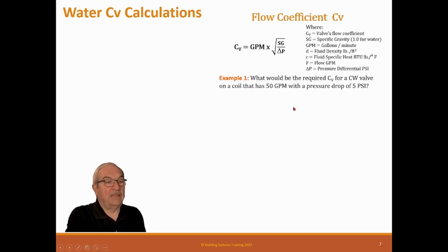Okay, now we're going to talk about some basic engineering stuff on control valves. A lot of people size control valves absolutely incorrectly. And I've talked to them blue in the face. Some of them just don't get it. But the pressure drop, here's where we get into trouble. This 5 PSI drop, a lot of engineers and designers have a standard spec item that says all coils, all control valves will be sized at 5 PSI. Well, that's an incorrect statement, because the valve should be sized to be equal or slightly greater than the pressure drop of the load it's controlling.